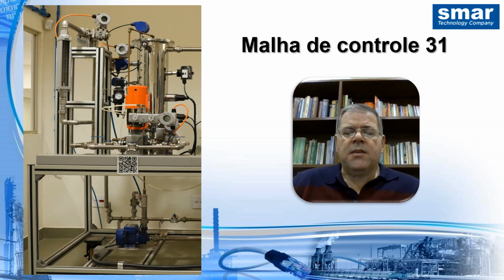Here we have a real photo of the mesh of one. So again, when the pump is turned on, the water enters the circuit going through a rotameter for flow measurement indication, goes through the electronic flow meter with an integral orifice, goes through the valve, equipped with a positioner, and enters the heating tank, returning either to the main tank or back to the mixing tank.